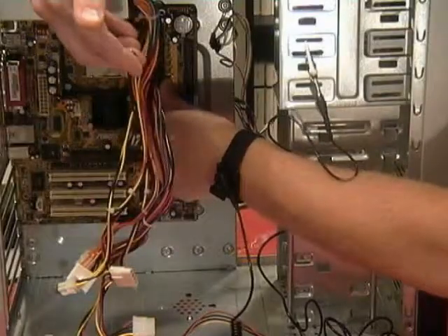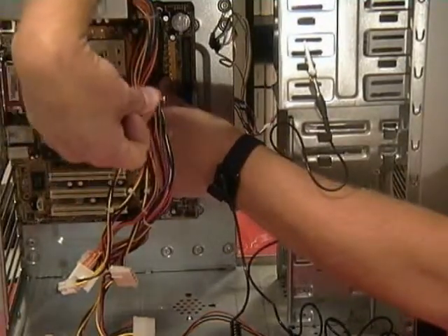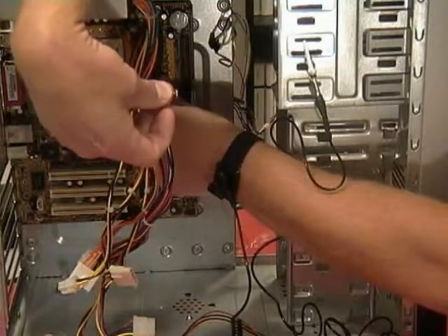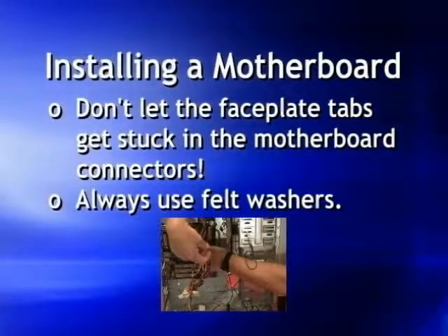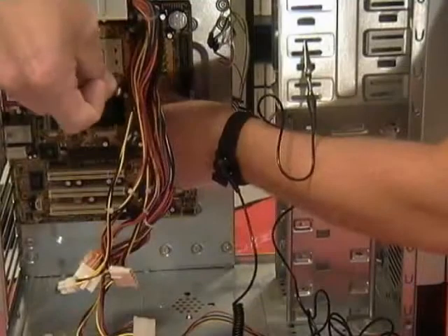The screws that we use are a little bit different. I don't know if you can see this shot, but the screw actually has a felt or rubber washer. It doesn't provide connectivity. We don't want current going through the screw from the case into the motherboard. So what we do is we put that little insulator on there to keep that from happening.